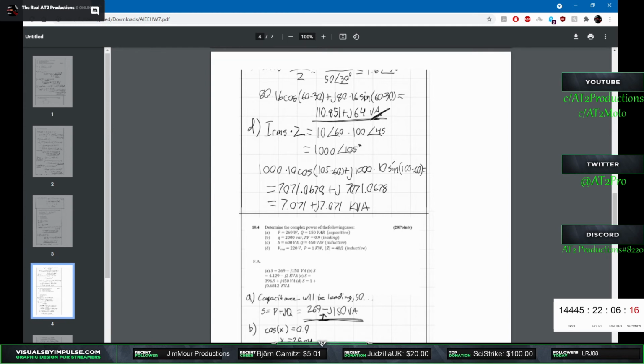Well, when you have a lot of inertia that the motor is controlling and you go into a braking situation, decelerating the load to a stop, the mass wants to keep going. Inertia is a thing you have to compensate for. Because of this dual conversion, as the motor is trying to stop but still spinning, you're actually regenning back through the motor onto the DC bus. You need to bleed off that extra current, and that's where the dynamic braking resistor comes in.